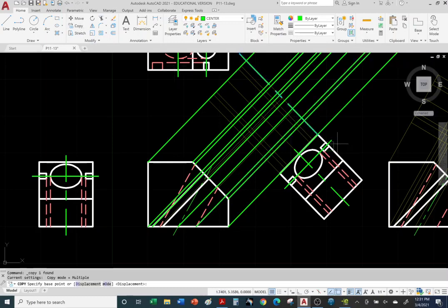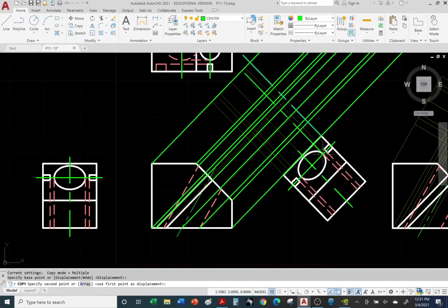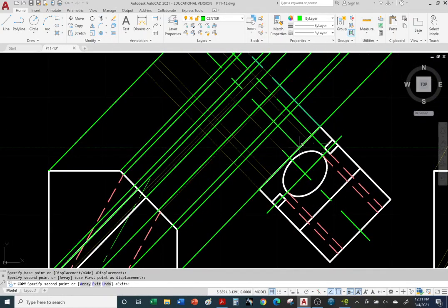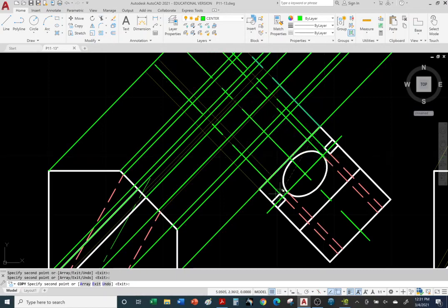And make copies so you can see how fast it is, and go to every corner to make copies, or to project I should say. Go to every quadrant, etc. So this is the way you would come up with construction lines. I missed some of them, but I think you guys got the picture. Okay, let me hit escape. Okay, so that's how you do construction lines.